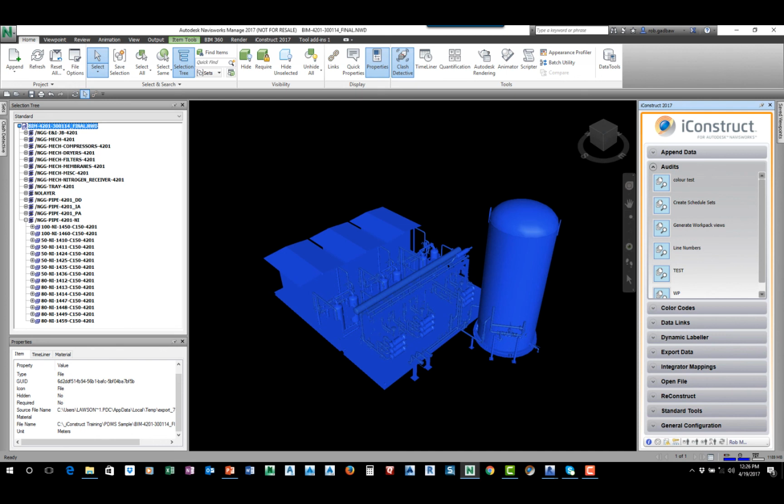Where I showed you that BIM flow earlier that takes 15 hours, that BIM flow loads 178 different models, mainly from Revit. It loads those models up from all the different subcontractors. Then we use the Audit tool and break up the model by the levels. So this will create viewpoints of every single level. Then we use the Reconstruct tool to export each of those viewpoints out as its own brand new NWD. So now I've got a smaller model with everything on level 1, 2, 3. Then we open those back up and run the clash detection, the reporting, the color coding, the status tracking, all of that kind of stuff. All in that one BIM flow. It'll do all that stuff.